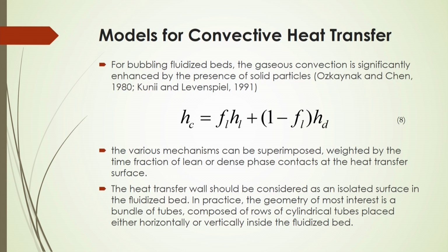Now, what are the different models by which you can express or analyze these heat transfer coefficients? Let us consider first the convective heat transfer coefficient. For a bubbling fluidized bed, the gaseous convection is significantly enhanced by the presence of solid particles, because of which there will be an enhancement of heat transfer in this bubbling fluidized bed phenomenon. In that case this heat transfer coefficient is denoted by f_L h_L plus (1 minus f_L) into h_d.